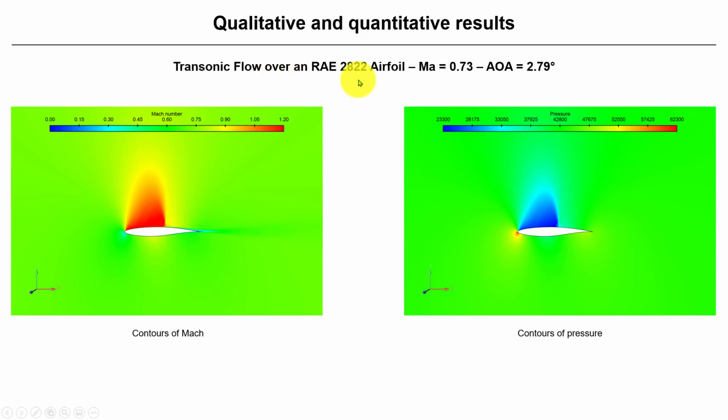And these are the results that we're going to get. We're running this airfoil at this Mach number and this relative flow angle, so there is no massive separation, nothing like that. We look at the contours of Mach number and see that we're in supersonic conditions. We have here the clear shock wave, and here the contour of pressure. See that you also have the change in pressure as an indication of that fingerprint of the shock wave. This is more severe physics. Dealing with shock waves is not easy, but Fluent is very robust and it's going to give good solutions.